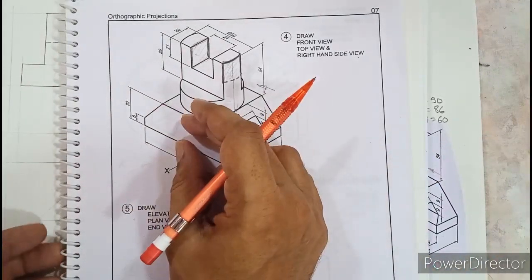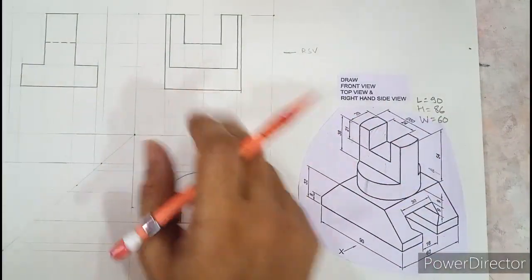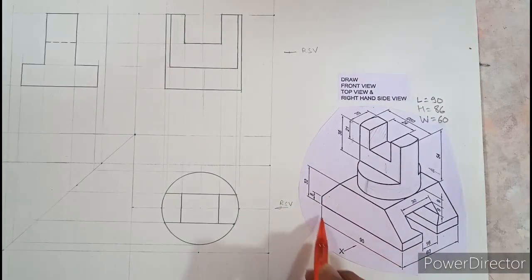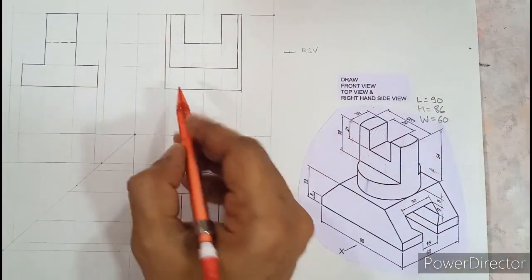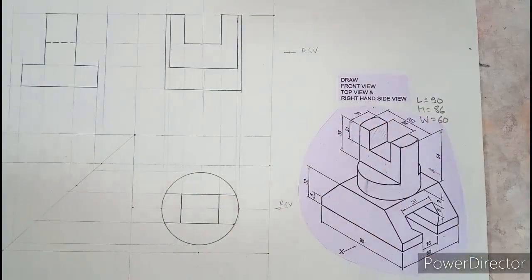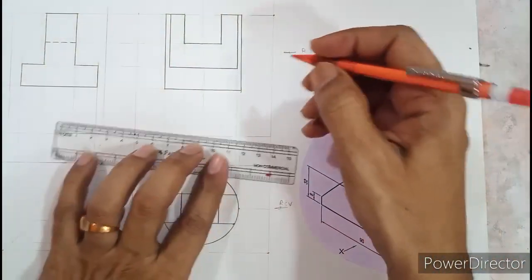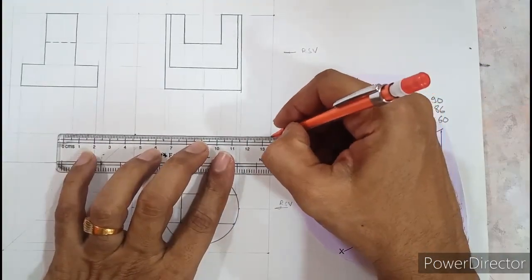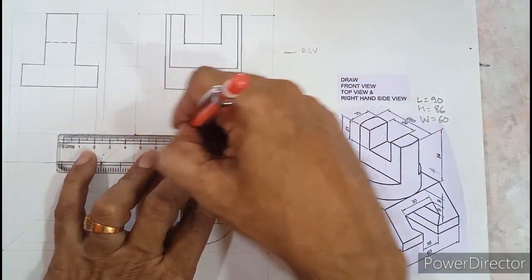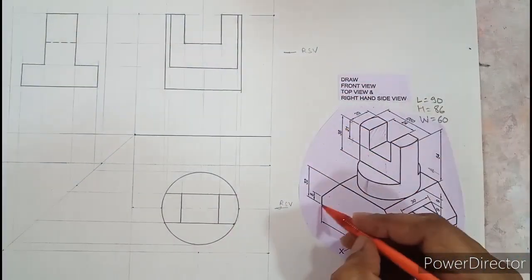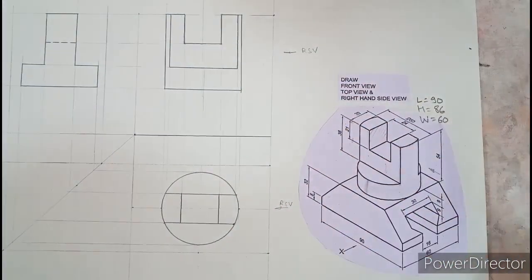So we need to draw this front view of the platform here. You can see in this diagram also, this trapezium type platform, we need to show it here. So see, 50 is already ready with us. Now we need to draw the bottom edge, that is 90 mm. So here we will draw an edge of 90. We need to raise this by 8 mm height. So the platform is 8 mm high.